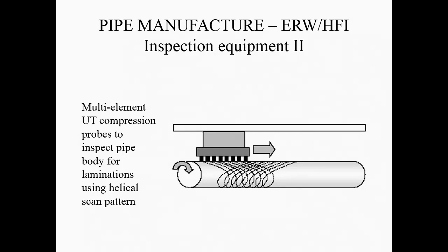It's based upon a moving ultrasonic array along the pipe. It's not a fixed system. This helical scan pattern is very useful because it can be set up very precisely in a factory situation. It's not something you would want to do in the field or on a lay barge or anything like that, but you can use that as a very simple way to check, because you're really only looking at what's happened along one line, along the top here. By the helical method, you're getting different angles, which will give you different information at different points along the surface, and you can depth scan the defects, which is what you need for lamination and for lack of fusion defects.